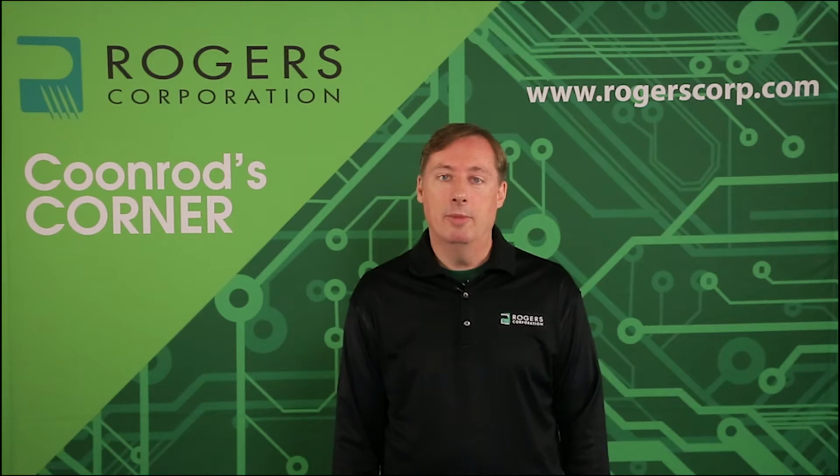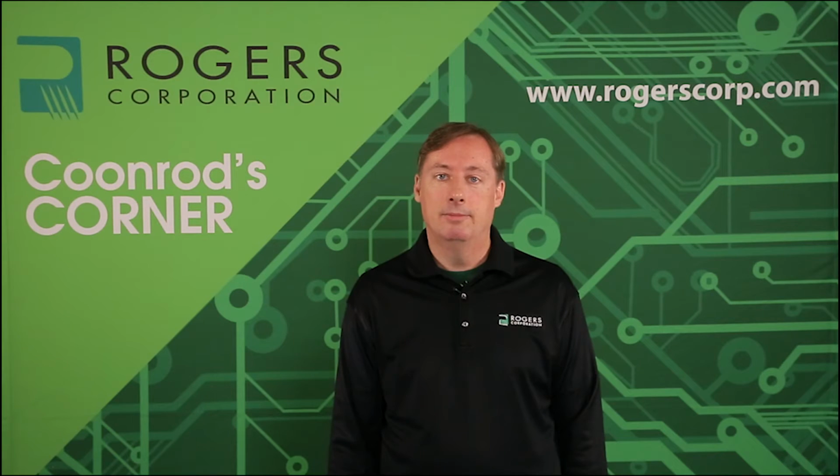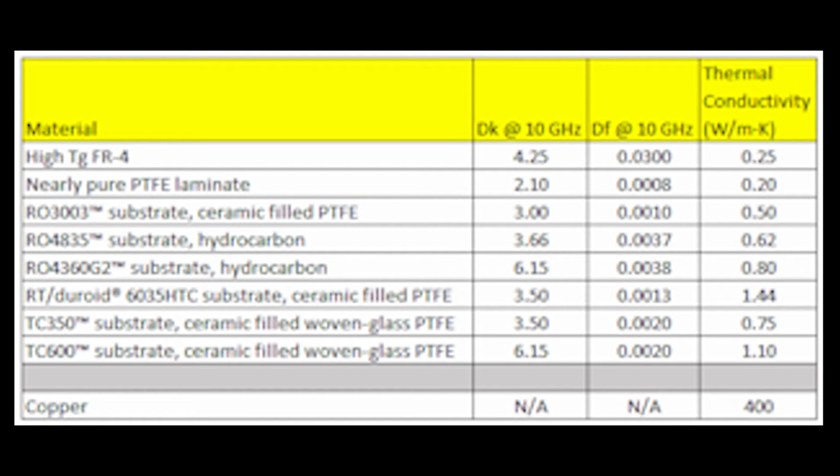So I've put together a table of information that gives a highlight of some of the materials used in the high-frequency industry where thermal management can be a concern. The table of information shown here is a combination of materials that are used in the microwave world for any type of applications that are high power or thermal management in general. And I do have the high Tg FR4 in here, and even though that's not a microwave material, many times it's used in combination with high frequency materials as a hybrid multilayer, and knowing the thermal conductivity can be important. In this case, I've estimated the thermal conductivity to be 0.25 watt per meter K, and it really depends on the type of FR4 that you're looking at. Some are a little better, some are a little worse, but the 0.25 watt per meter K is a pretty good number in general.